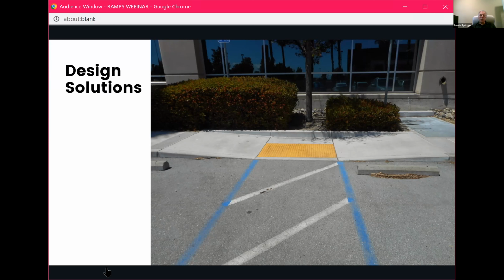So here's a great example of a parallel curb ramp. This looks just like the image in the code. You have two sloping ramps coming down to a landing. I think this is actually a little older code, so we don't actually have the 36 inches behind. If you're looking at doing path of travel upgrades, this can start affecting some of the path of travel upgrades, because if this isn't completely compliant, you're going to need to look at moving this curb face back to allow a 36-inch space in between the detectable warning and that back of curb.